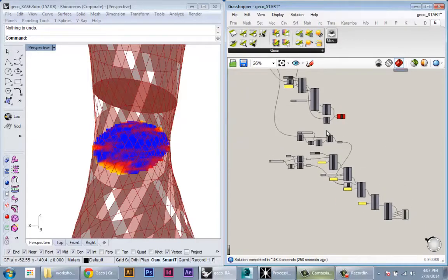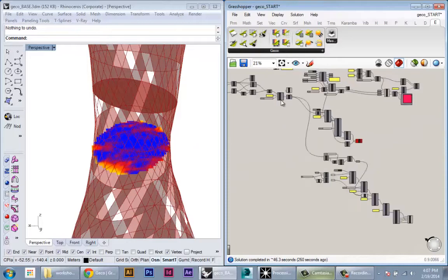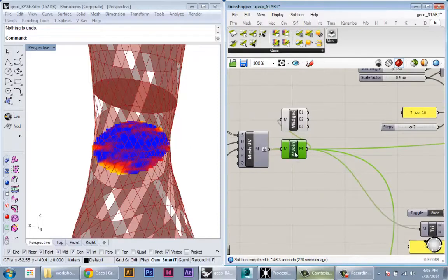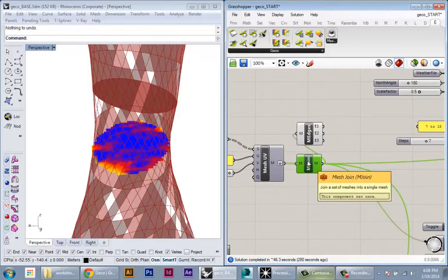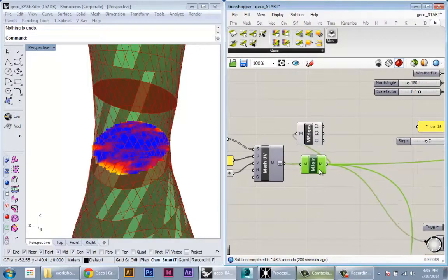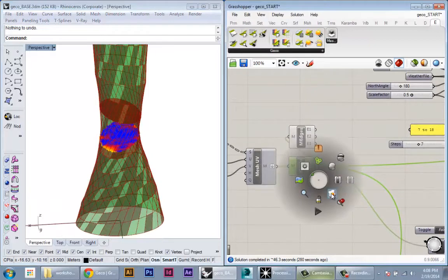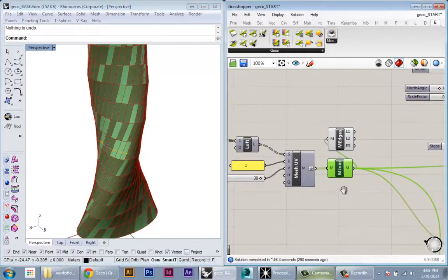your building. Okay, so the first step of this, since we're working mainly in Rhino and Grasshopper, is exporting geometry from Grasshopper or from Rhino and bringing it into Vasari. Vasari uses mesh geometry, which is really good because we're already mainly working with meshes for our other types of analysis. So to really bring in your form, all you really have to do is select the meshes you want from Grasshopper, and then you bake them into Rhino.